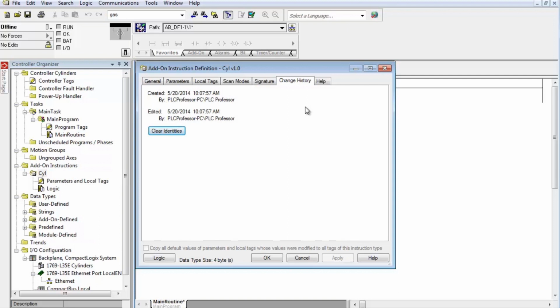An add-on instruction is executed just like any other routine belonging to a particular program. Because another task can preempt a program containing an add-on instruction that is being executed, an add-on instruction may be interrupted prior to completing its execution. In standard programs, you can use the user interrupt disable and enable, UID and UIE, instructions to block a task switch if you want to be sure the add-on instruction executes uninterrupted before switching to another task.